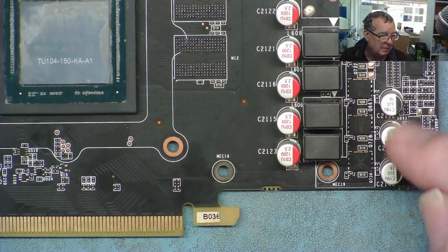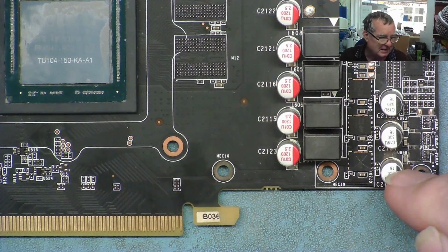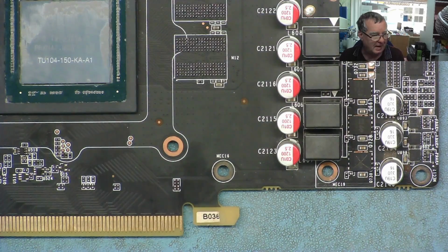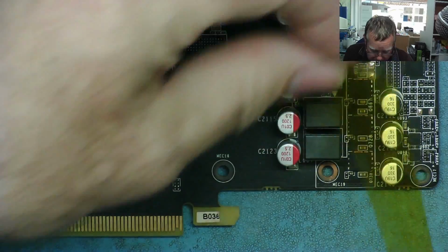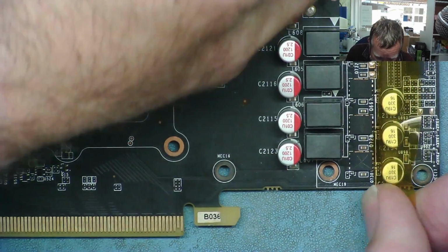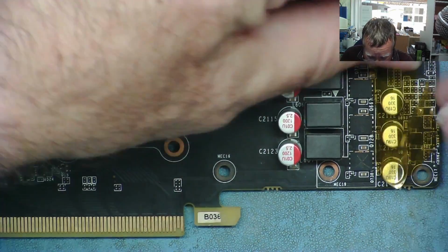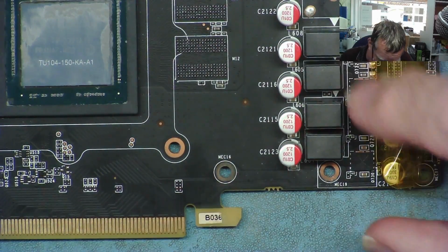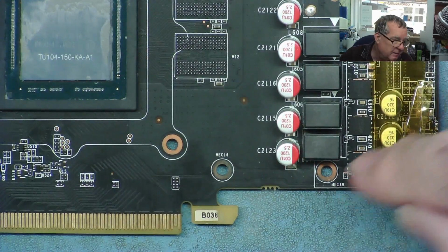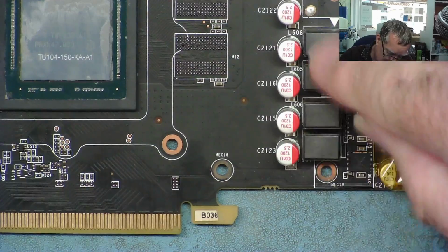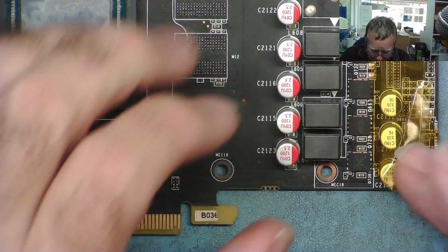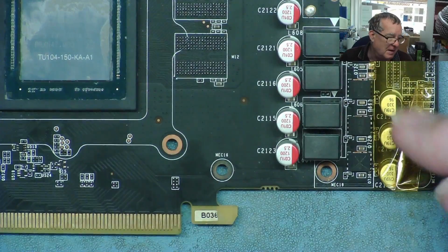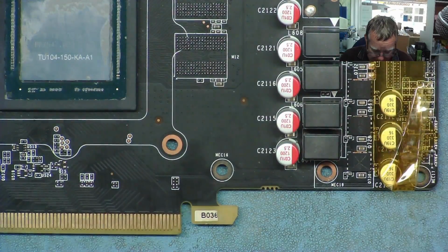Bear in mind there's a lot of capacitors around here, and if you get too much heat into these, they'll bulge, in which case they'll fail, or they'll go bang and make a mess, and they don't smell very nice. So the first thing I'm going to do is just cover over these with a little bit of Kapton tape. Aluminium foil is also quite good for this. So I'm going to try at least to protect them from the heat. I'm also going to come in with the heat from this direction as best I can. So I'm trying to keep the heat away from these a little bit. Having said that, I may still end up having to remove at least these ones at the end.